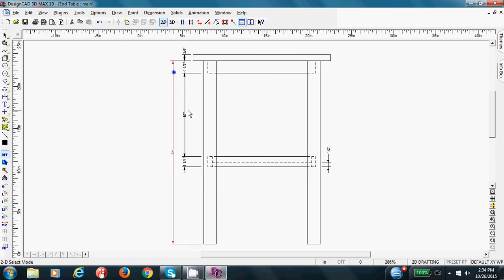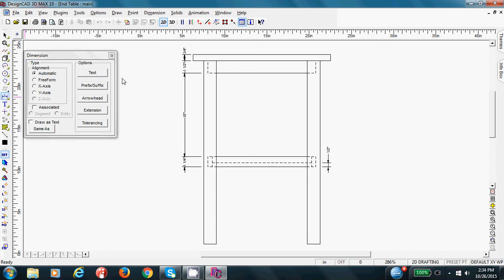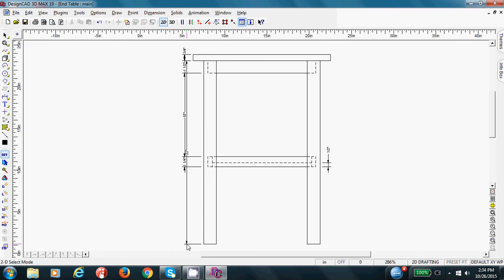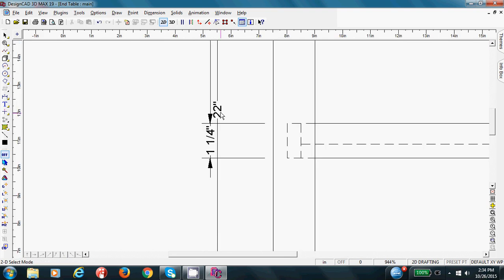Okay, so let's place it with point relative. Right click, and let's try point relative, quick key, -2, and see what happens. Now, -2, it went -2 from, I believe, this point here. In this case, we could do the math and figure out exactly how far and where we want it, but this is currently incorrect because that's not where I want to place it.